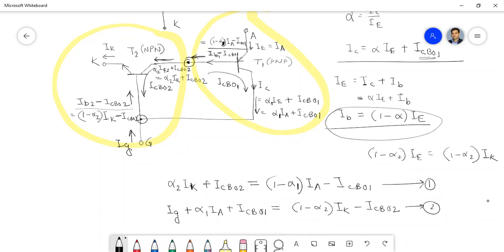If you remember from your discussion on transistors, if the base emitter current flows, then the transistor becomes on and the gain of the transistor increases. So when transistor 2 becomes on, its gain, alpha 2, increases. Now if alpha 2 is increased, what about alpha 1?